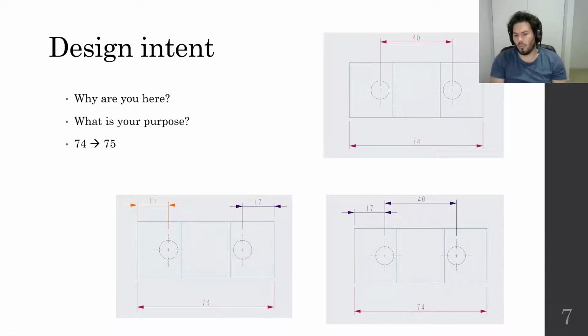So, which one of these is acceptable? This entirely then depends on what this object's application is in life, right? So, if there's already two pins sitting somewhere 40 mils apart, and it has to slide over the top of them, then that's not acceptable anymore. That might be, well, both of them are, but that one's not. But maybe it needs to be symmetric. Maybe this one's no longer acceptable.